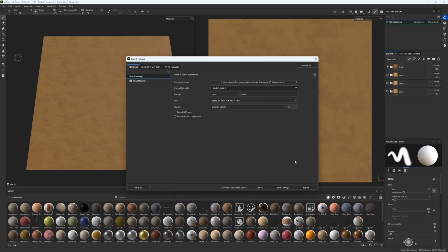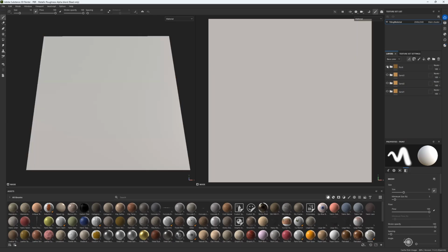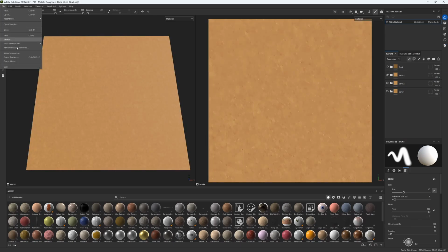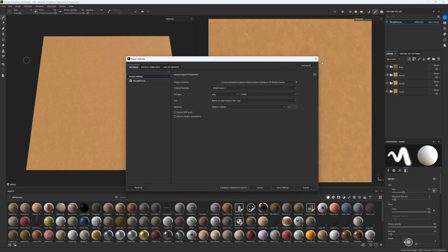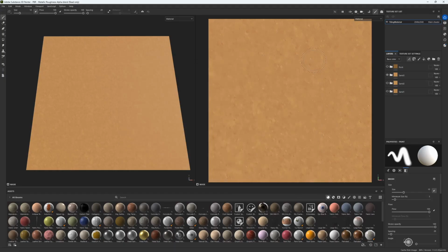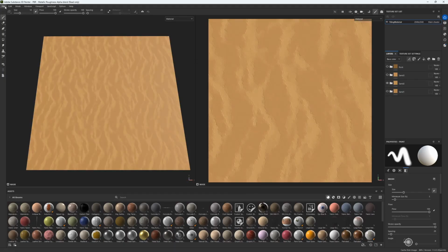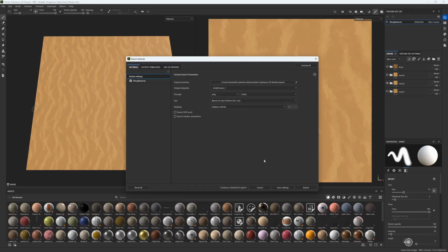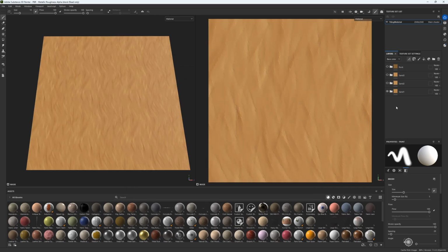When you want to export the next texture, just close this one, hide the rock and unhide the sand, do a file, export textures. Now it is going to override the previous material that you exported because it will have the same name, so make sure you go into your folder, change the name to rock or rock texture, rock terrain, and then do the next export. Hide it, unhide sand 2, make sure to change the name in the folder, file, export textures, and repeat that. So we should now have 4 sets of exported textures for the Unity terrain.